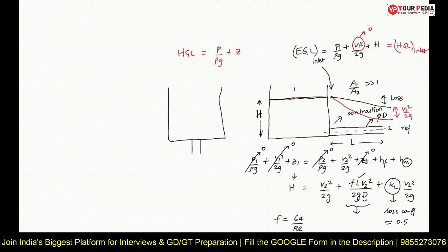See, you are doing some mistake here. Actually, the total energy of the fluid at the exit is going to be zero here. Why so? Because the analysis which you have done is perfectly correct. There is no need to worry. Here, the V square by 2g is the exit loss. I accept that we have kinetic energy at the exit, but we are not utilizing it, so it is going to be considered as the exit loss here.